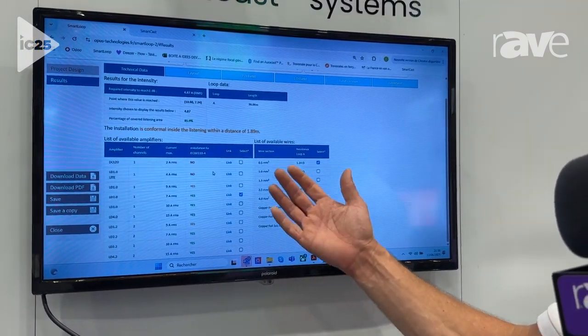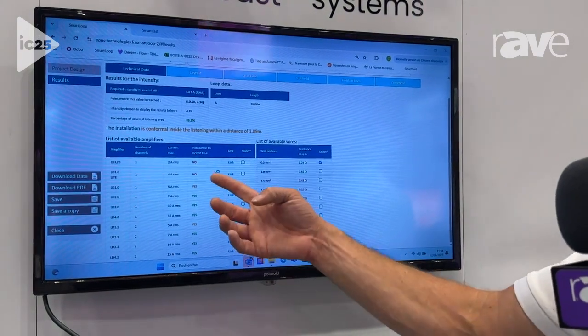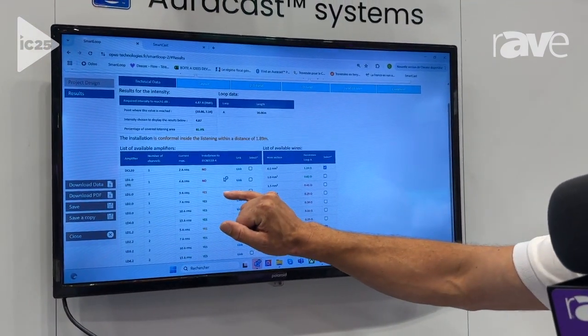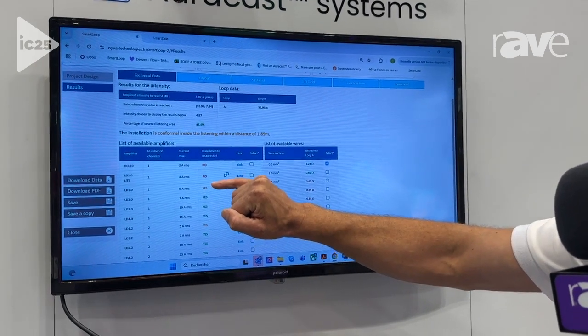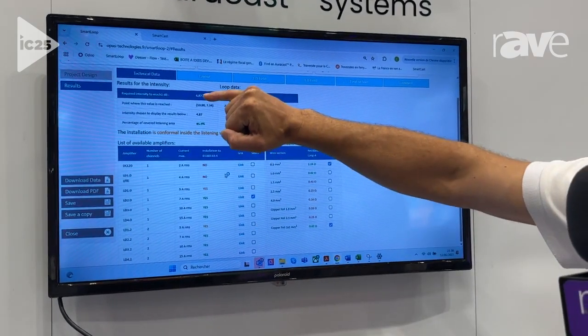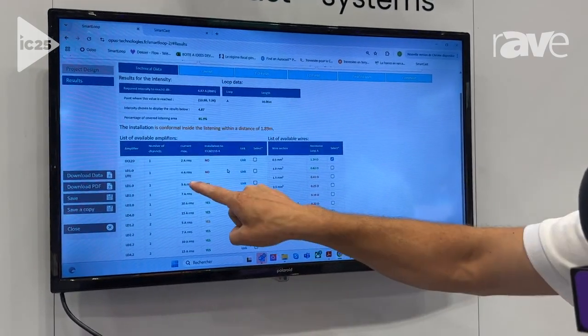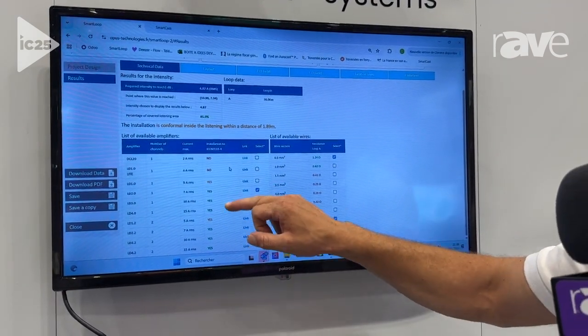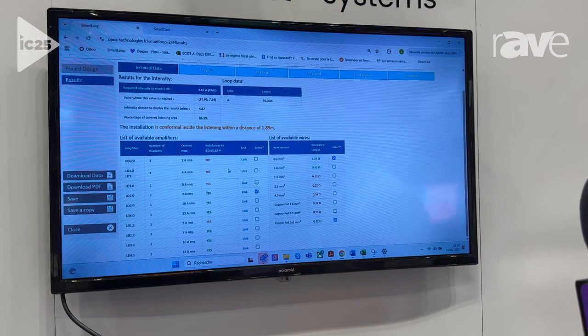So on this project, for example, we can see that the LD 1.0 lite, which is a 4 amp amplifier, would be too light. You should go for an LD 1.0, and yet it's still a little bit too light. We need like 487 amp, and the max of our amplifier LD 1.0 is 5 amp. So we recommend you to go for an LD 2.0.